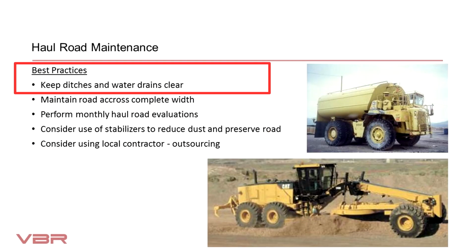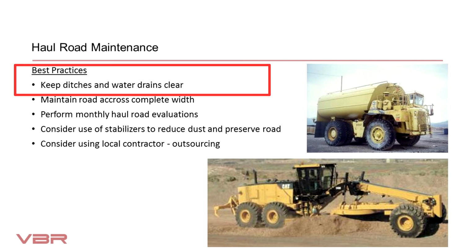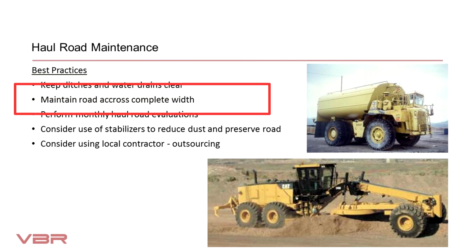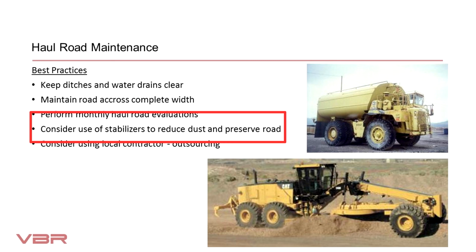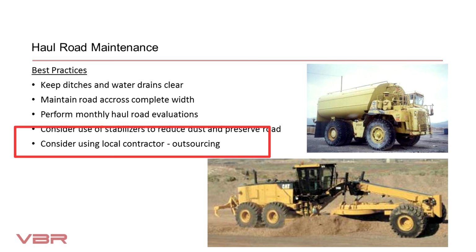There are some best practices to remember in terms of haul road maintenance. For instance, keep ditches and water drains clear. Maintain road across total width. Perform monthly haul road evaluations. Consider use of stabilizers to reduce dust and preserve roads. Consider using local contractor, outsourcing.